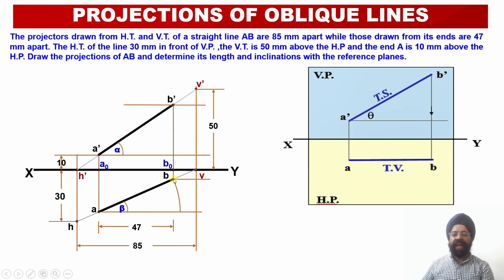This is the direction of the movement of this plan projection line. So I will be rotating it through this particular distance such that this AB line is brought parallel to the vertical plane. So the new point is obtained, B1. Now I have been able to obtain the plan projection apparent length AB1 parallel to the vertical plane.